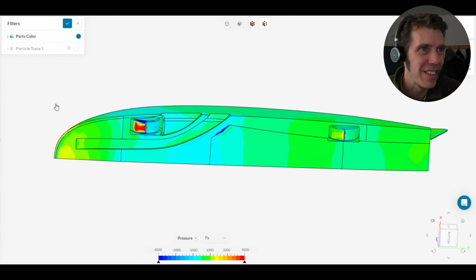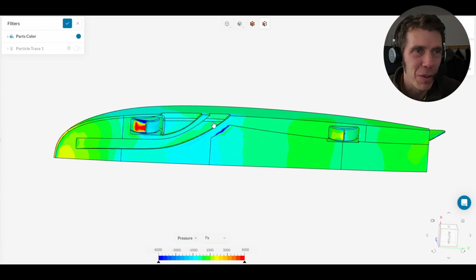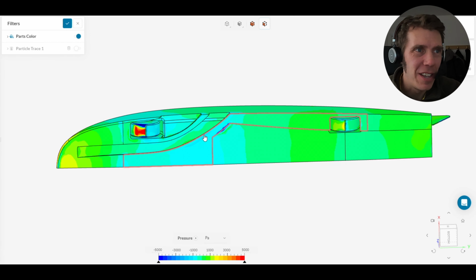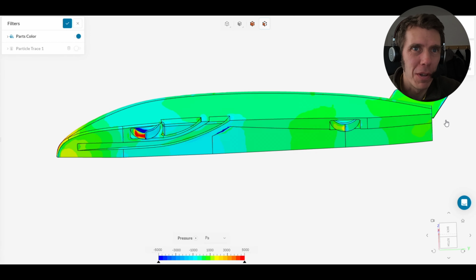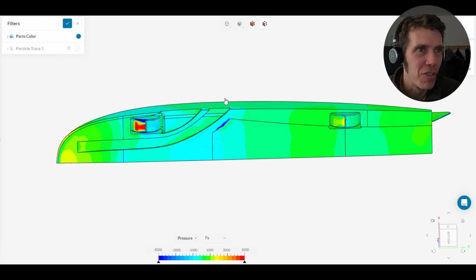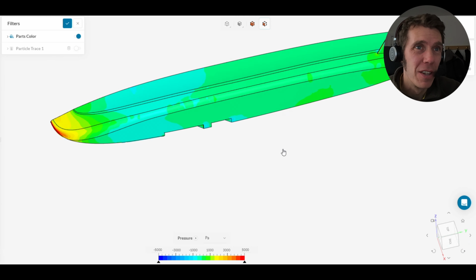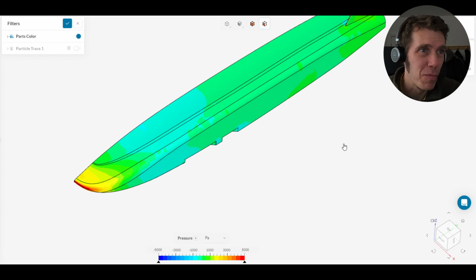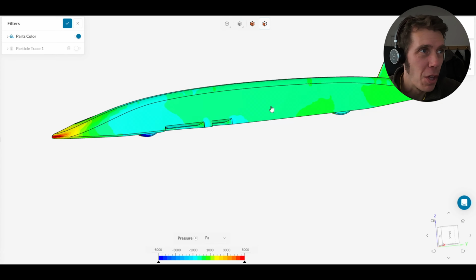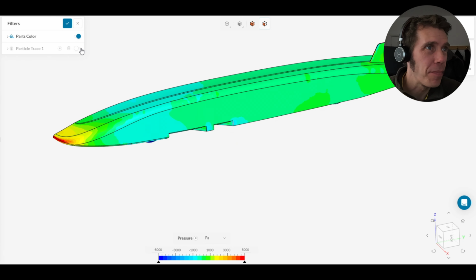So you can see it's got a vent that goes through from the front and out to the side, and it's got some cutaway behind the front wheels there, and then the underfloor turns into a bit of a diffuser shape as it goes rearwards. So we've got quite a nice area of lowish pressure underneath there. On the upper side it looks the same as before, no great surprise because I didn't change it.